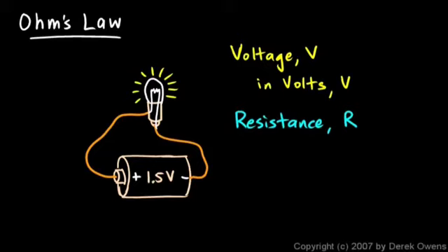And things that you put in the circuit, for example, the light bulb, has a significant amount of resistance. The wires have very little resistance, which is exactly why we use them. In fact, the resistance of the wires is so small compared to the resistance of the bulb that we consider the resistance of the wires to be zero. That's really a good approximation. It's not quite zero, but it's really close. So it's a good approximation to just ignore the resistance of the wires.